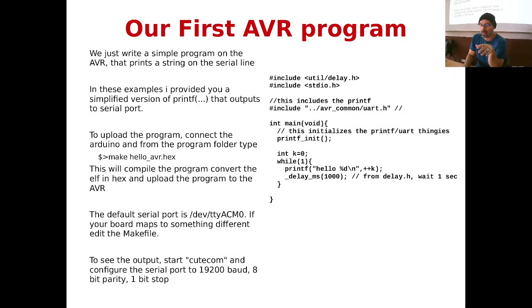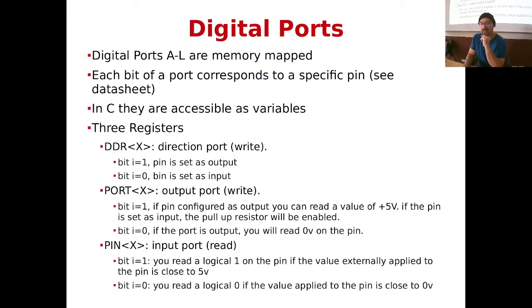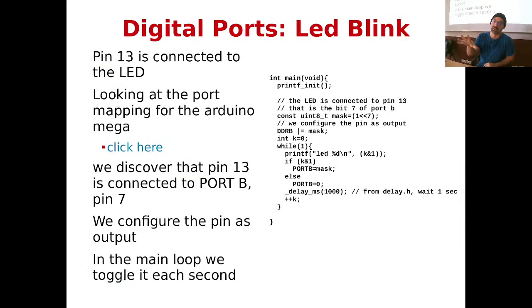We furthermore introduced some basic concepts. The printf, which today we will go into more detail, allows us to write data on the serial line that we can then monitor with the serial monitor to figure out what the machine was writing. And we were stressing the aspect of the digital ports. In particular, I've given you 2 examples, one for the LED blinking, which is an example on how to configure a port as output.